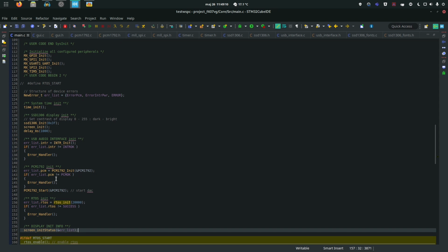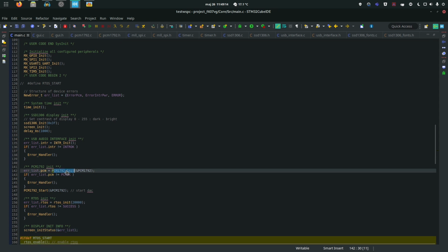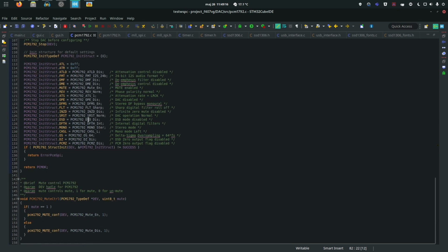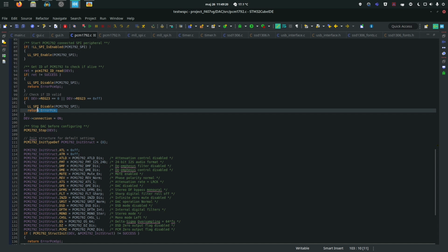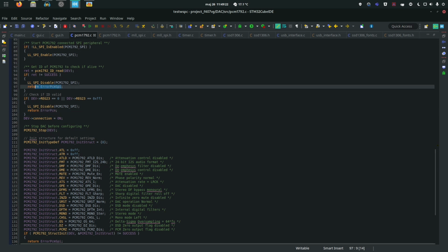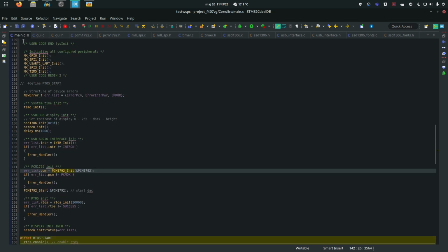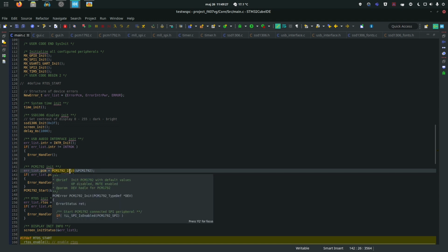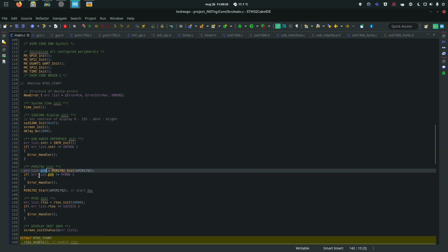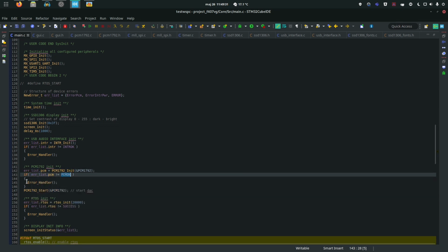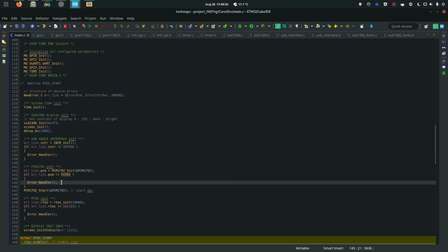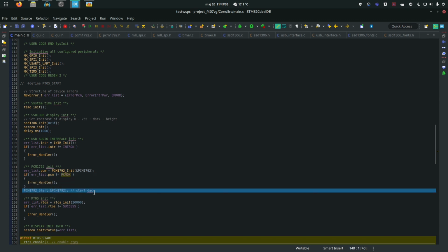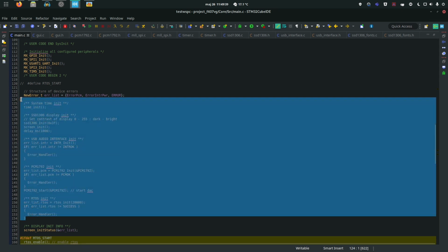I have a little bit of error here that I would like to discuss. So the PCM initialization, we already saw that the PCM initialization over here can return the error or the SPI or the device error over here, or even the SPI over here. So it also gets fed its error, whether okay or not, into the list. And if this is not okay, then something should happen. Over here you can see there's the start function. So this is wrong, because here I'm just in the initialization section.